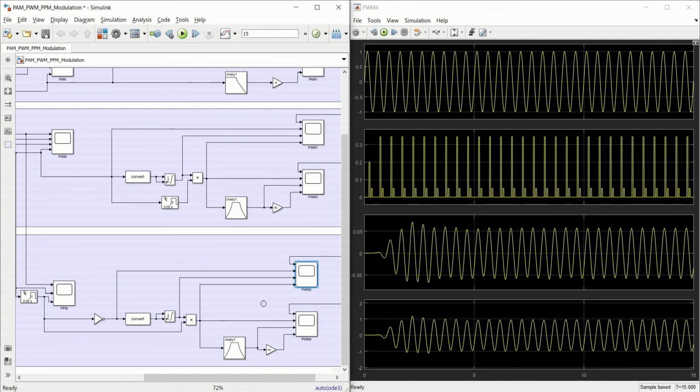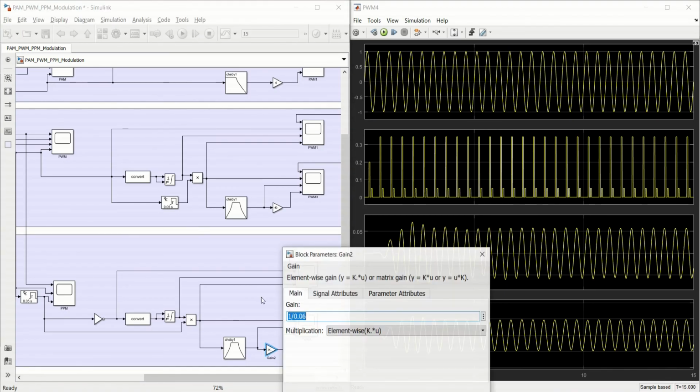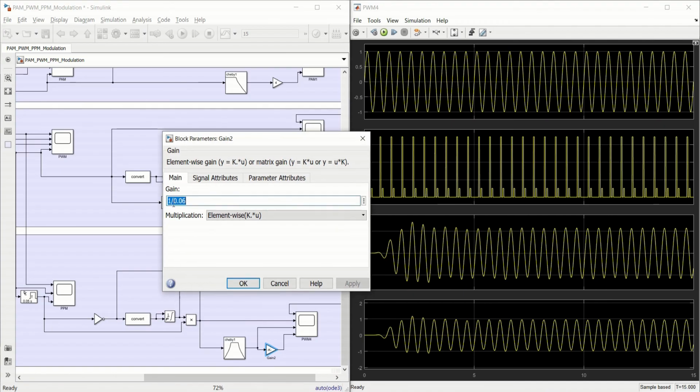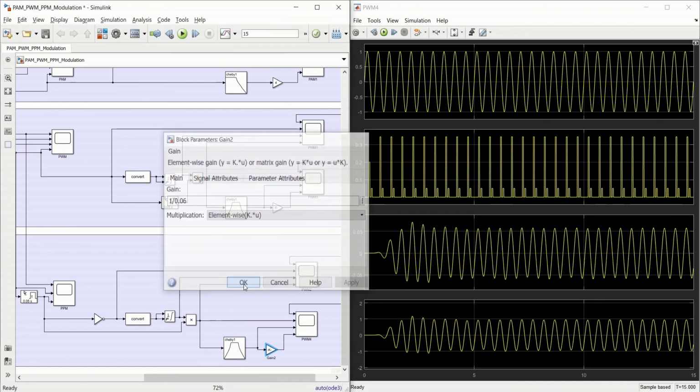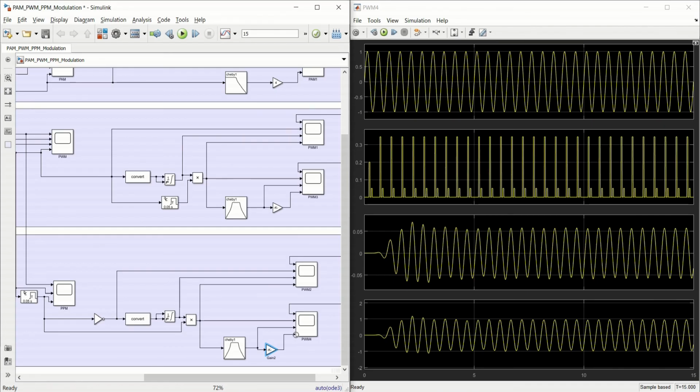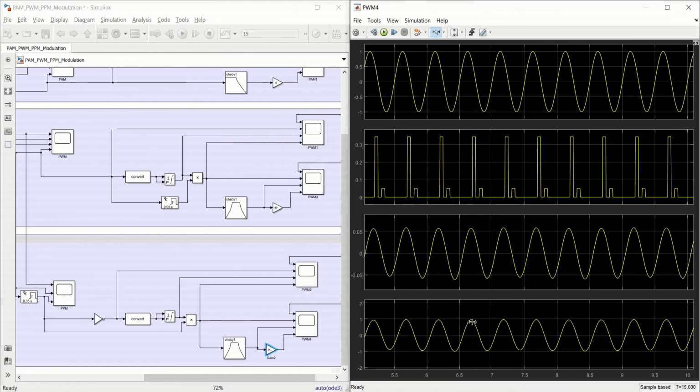And you can observe that because of the characteristic of this band pass filter, we have an initial tracking delay, and after some time we have a stable region, and lastly we have a gain k with this parameter, which is then fed to the fourth input of this scope, which is over here. So let us zoom in on some of these values, and we can observe that using this demodulation technique of pulse position modulation, we have recovered back the message signal.